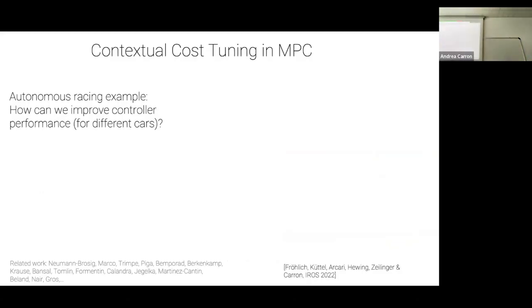In the example that I showed you, what we're performing with MPC is a path following controller, where we incentivize to progress along the path as fast as possible. But this is different from performing racing, so minimizing the lap time. And tuning such that the car really goes as fast as possible is not an easy task. This controller is not super easy to tune.